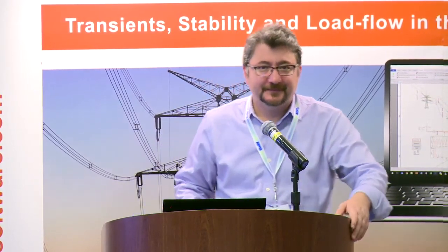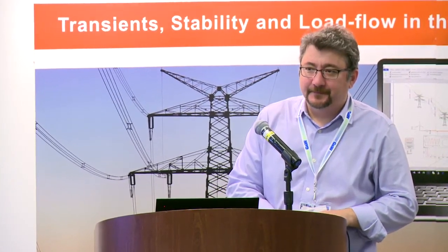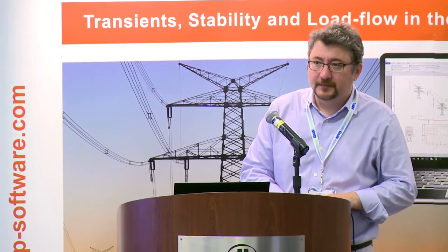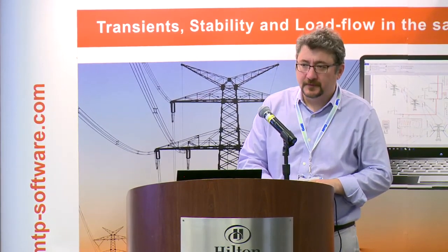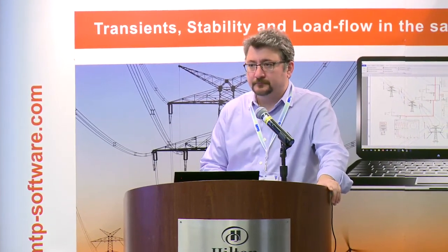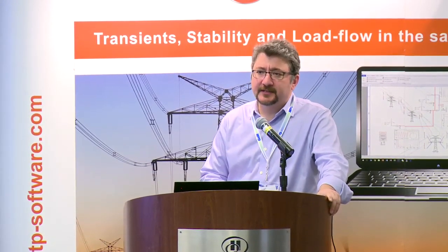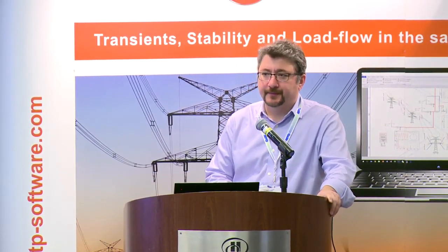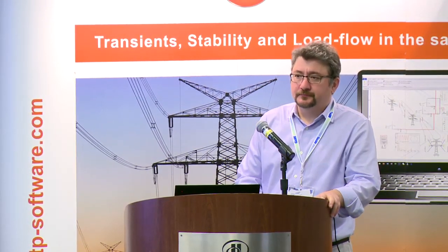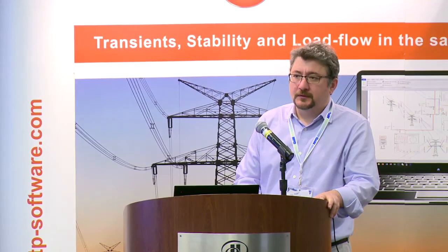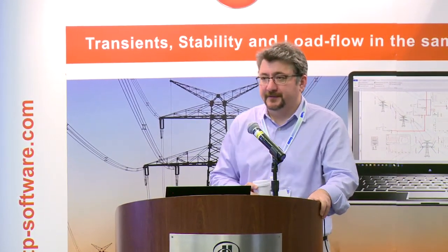Any questions? We have time for one question. When you apply the vector fitting technique, we know that vector fitting is a pole relocation technique, right? Yeah. So how do you decide how many iterations you apply in this pole relocation? You increase one by one and you check. So you calculate poles, one iteration more, you calculate also residues, and you check the RMS error? Exactly. So the number of iterations is not fixed? No, it is not fixed.